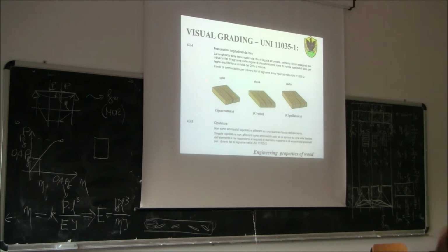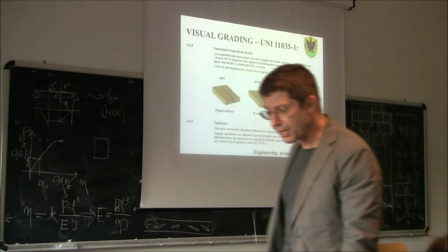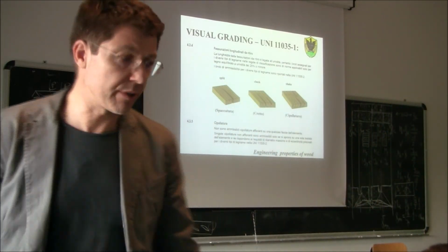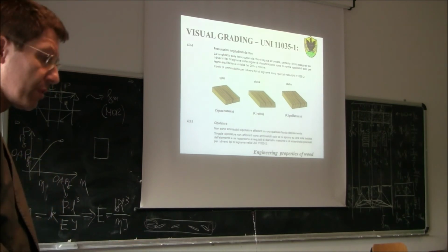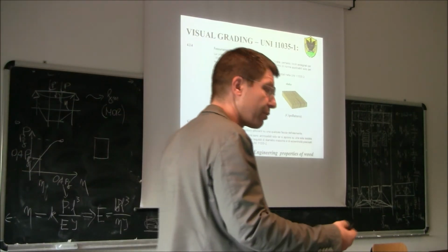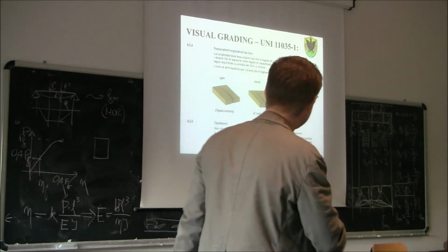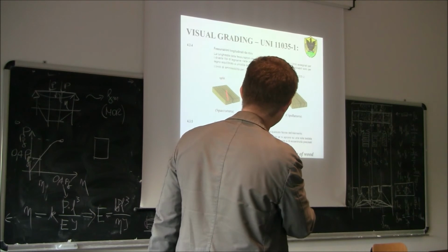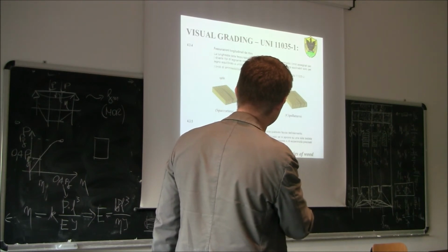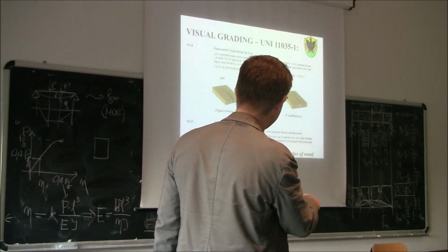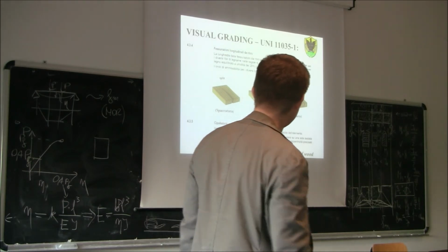And then another thing that we need to check is about these cracks. Those cracks we will learn later. Often they are due to basically shrinkage of wood. So when you dry the wood, you will see that there's a strong effect of moisture content. So usually the wood must be dry. When the wood is dry, then you get some cracks. It will be split if the crack extends to all the thickness, otherwise it's called check or shake. This is in Italian cipollatura.